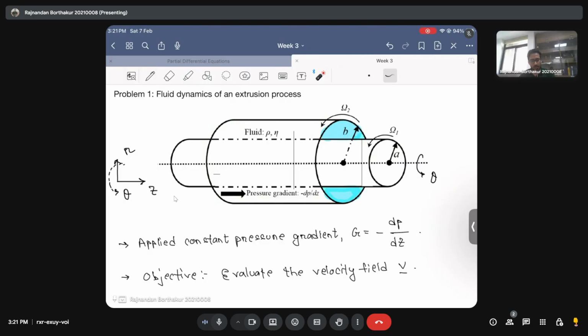So what you then do is apply a pressure. What is done in the industry is that a pressure gradient is applied such that the molten material comes out, and then this process can be repeated for the next cycle. Okay, so it's very simple. You first put the molten material in between the die, which is the case of two cylinders in this scenario. The shape of the die, as I said, depends on the end product that you are going to manufacture.